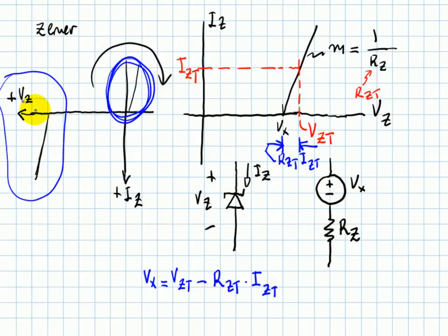That is where we find the Zener diode, and because we're going to be working there, we will define a positive voltage in the Zener diode with this polarity, and a positive current in the Zener diode with that polarity. That is, we're going to be operating somewhere on this line. That's why let's turn around this graphic and draw it rather like this. Positive IZ, positive VZ, and this is the line.